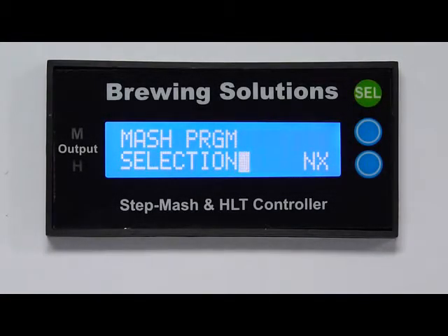In this video, I will demonstrate the PID Auto Calibrate operation of the step mash and HLT controller. Before calibrating your system, please read and understand the brew system preparation in the PID Auto Calibrate section of the instruction manual before proceeding. Please note that this is a one-time calibration procedure that will not need to be repeated unless a significant change has been made to your system, such as heater wattage or batch volume.